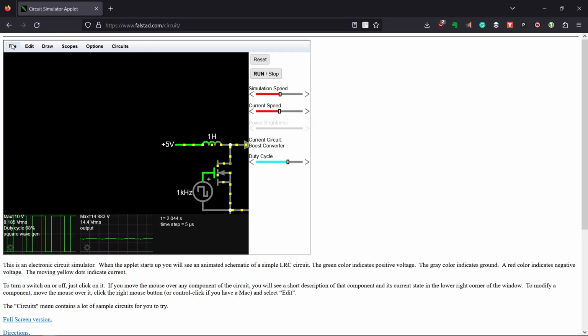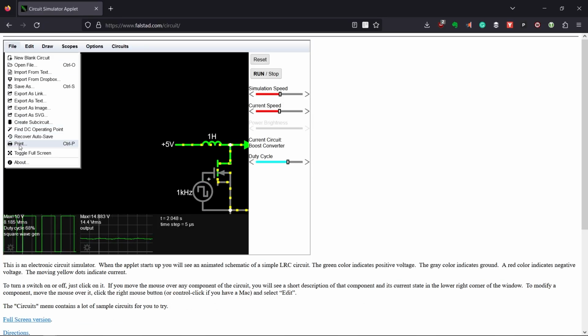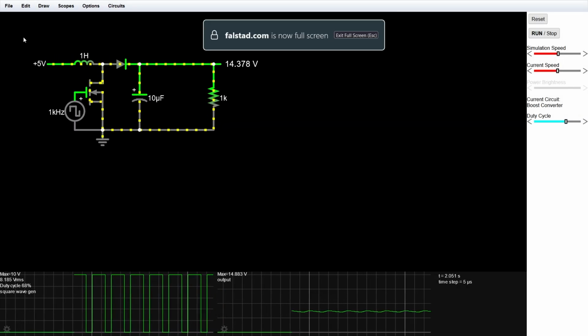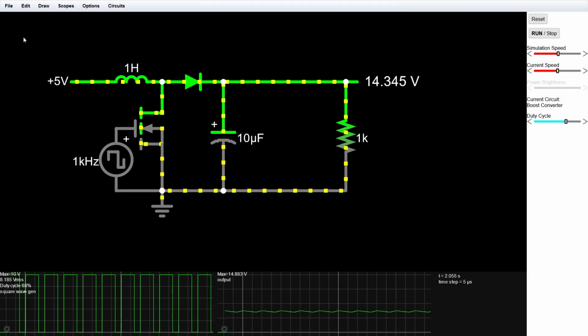When you think simulation, you might think of something like Falstad or other SPICE-based simulators. And SPICE is great for low-level analysis, but it is limited. In power electronics, you need to simulate at a system level and include domains other than electrical, like magnetic and thermal. And you're especially interested in the switching losses of the MOSFETs themselves.